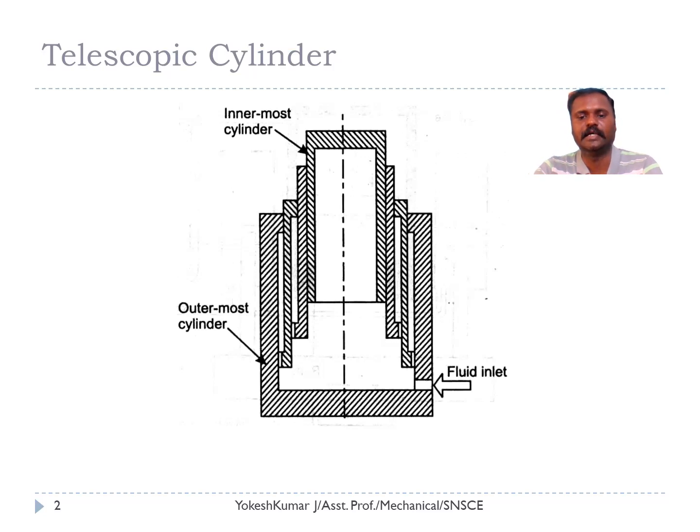So let us explain the working of the cylinder. In working, the pump pumps the pressurized fluid from the reservoir, and it is sent into the direction control valve, which directs the fluid to the appropriate port of the cylinder.